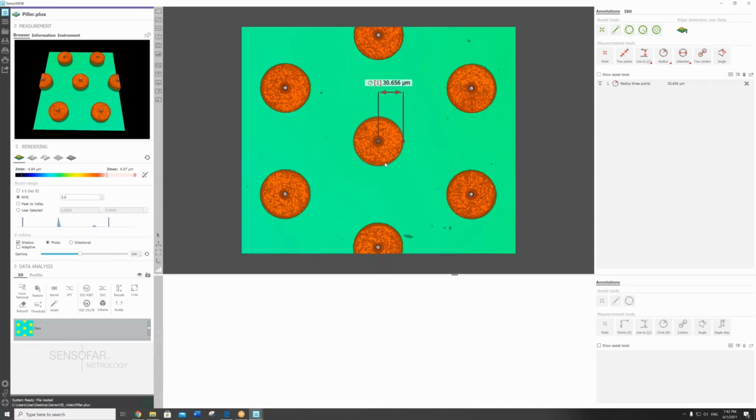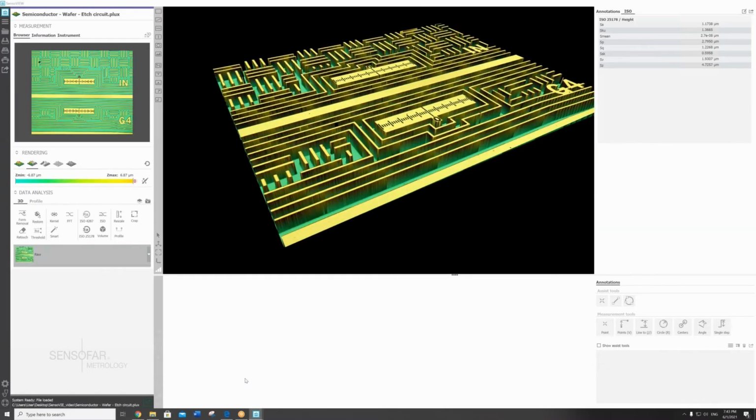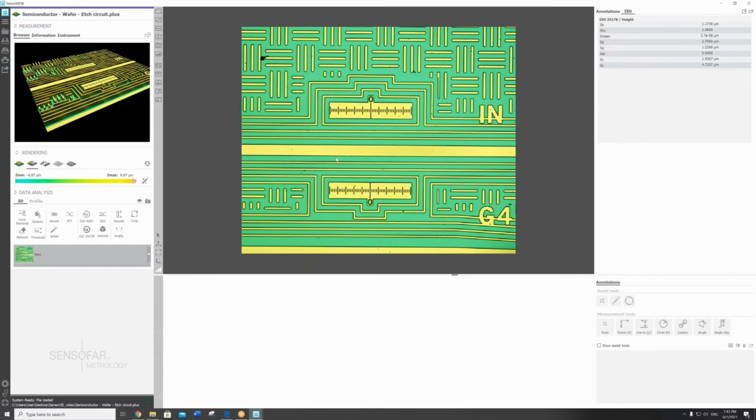So one of the consequences of having this edge detection is that the subjectivity of the measurements is going to be extremely low. So for example, if I take these measurements 3 times, I put the dots like this, I do it again, and I do it again a 3rd time, it doesn't matter where I put the dots. At the end, it does recognize the circle and the value will be the same regardless where I put the points.